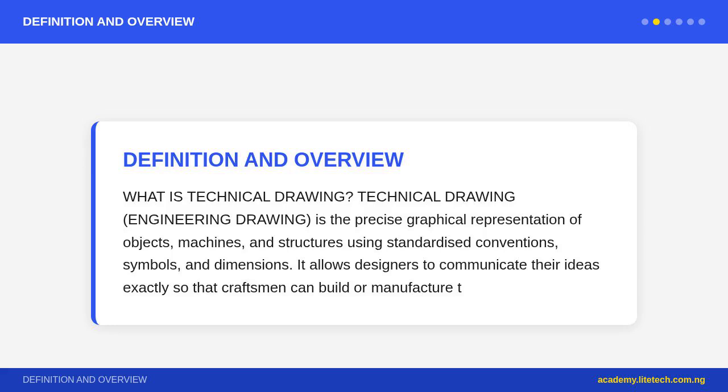The 60 degree or 30 degree set square has angles of 30, 60, and 90 degrees, and is used to draw lines at 30 degrees or 60 degrees. Both set squares together with the T-square allow drawing of any multiple of 15 degrees: 0, 15, 30, 45, 60, 75, 90 degrees.